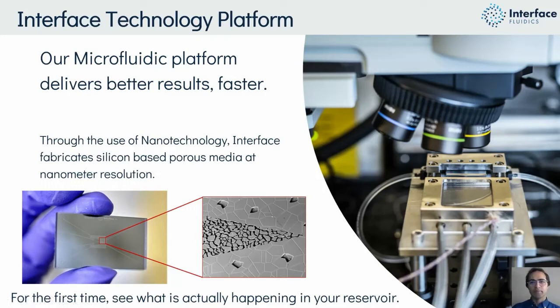Interface uses a technology which is called microfluidics. Fundamentally, microfluidics is the study of the fluid behavior at the micro scale, which is relevant to the porous scale of the hydrocarbon reservoirs. What we do is generate analogs that replicate the porous structures and geometries of the rock, and then we look at the fluid interactions and the fluid movement through these porous spaces using our optical tools.